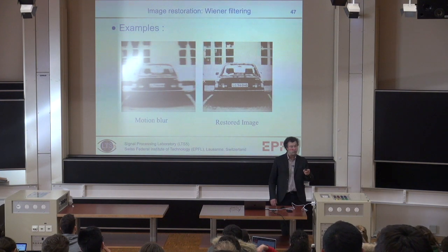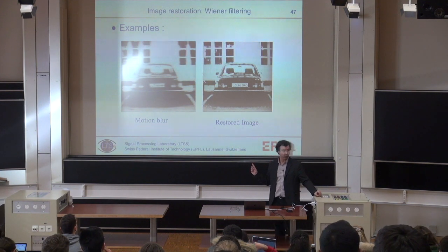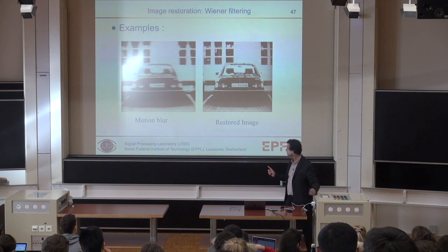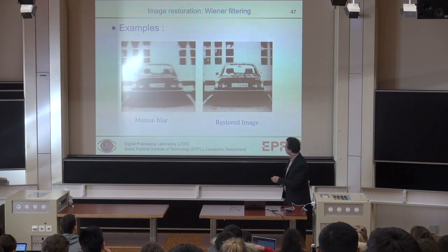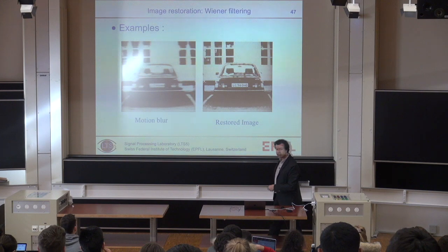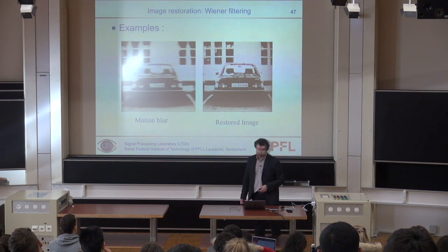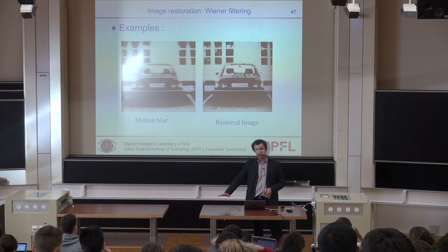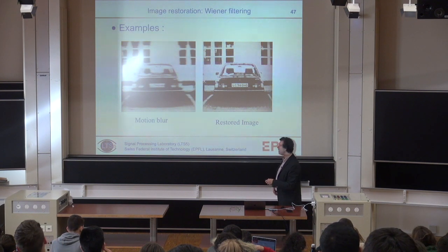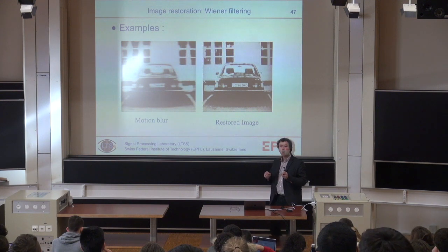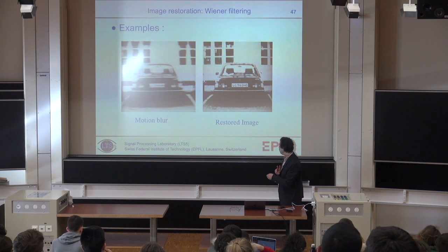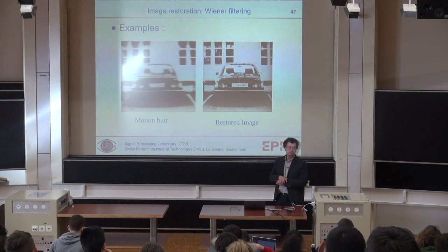You said deconvolution. Restoration is deconvolution. It's a synonym. We are doing deconvolution. Okay? It's exactly the same concept. I have a blurred image. It looks like all the details are gone. They are not gone. They are just low-pass filtered. If I restore them by high-passing this image for the frequencies where I estimate that there is not too much noise, I will have the ideal restoration.